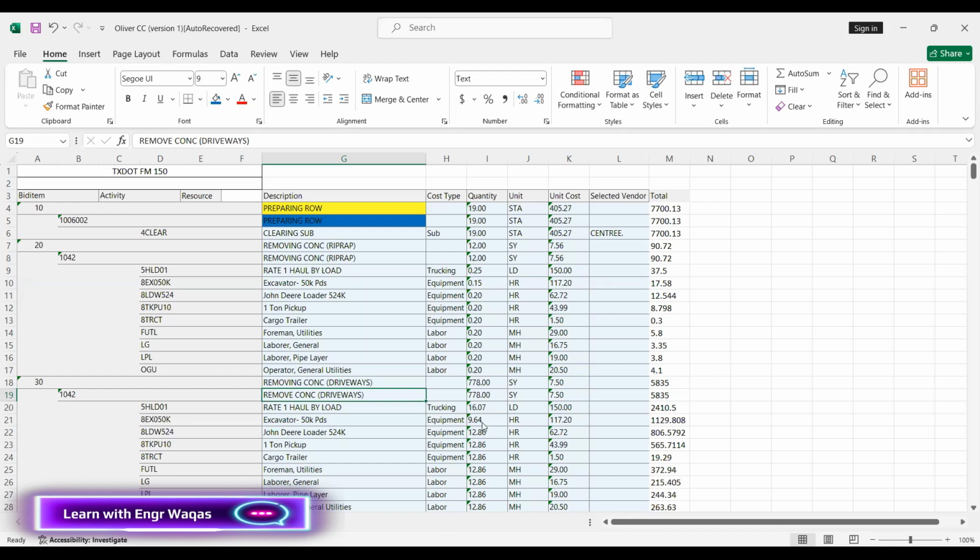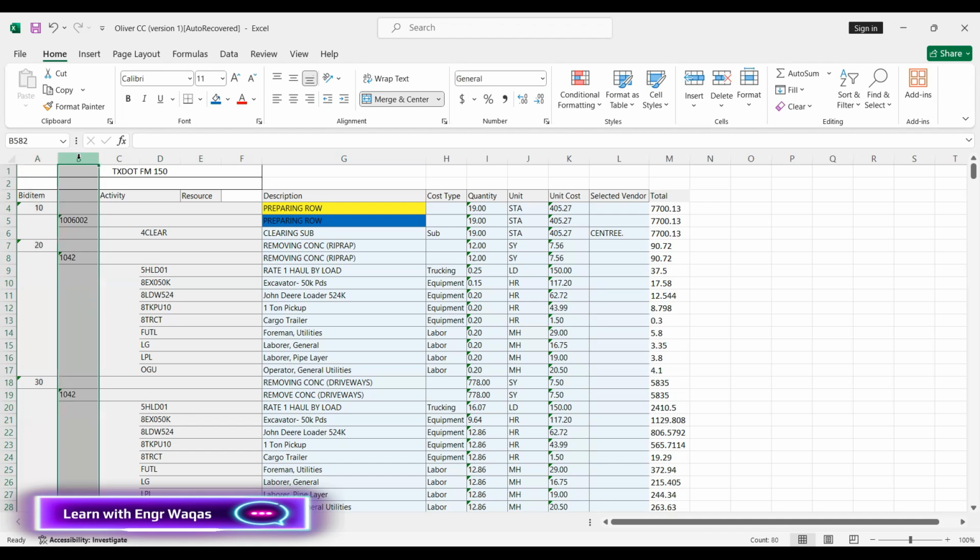So we have this Primavera P6 sample project, and behind that project, we have an assignment. Here we can see, one by one, column A, not against every single activity, but I will make you understand. This is the bid item mentioned in your BOQ or pricing. Then there is the cost account or cost code. Then there is, you can say, the resource code.